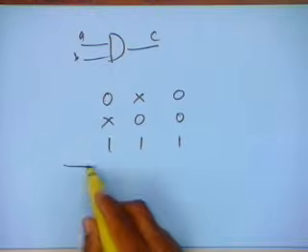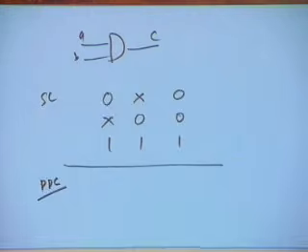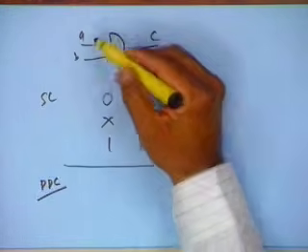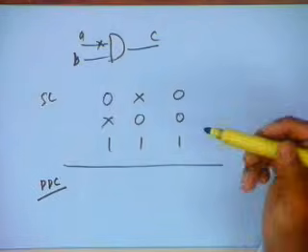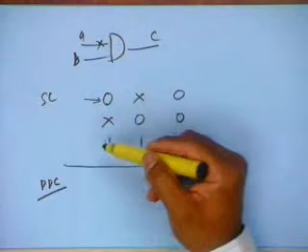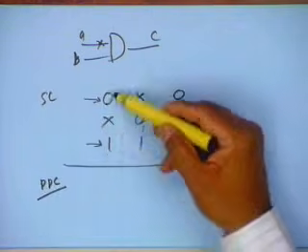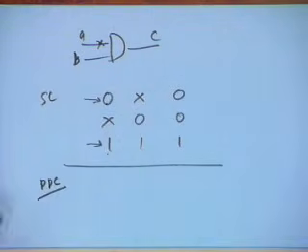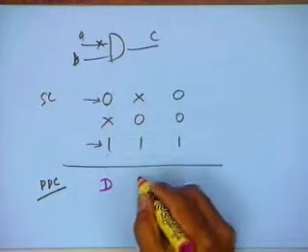What I want is a capability. So this is my singular cover. Now I am doing PDC, propagation D cubes. What I want is, if a fault appears with this input, I should be able to transmit the fault to the output. So I look at one row where this is 0, and another row where this is 1. Row 1, this is 0 and this is 1, and I take the D intersection of these two. What I will get is D 1.